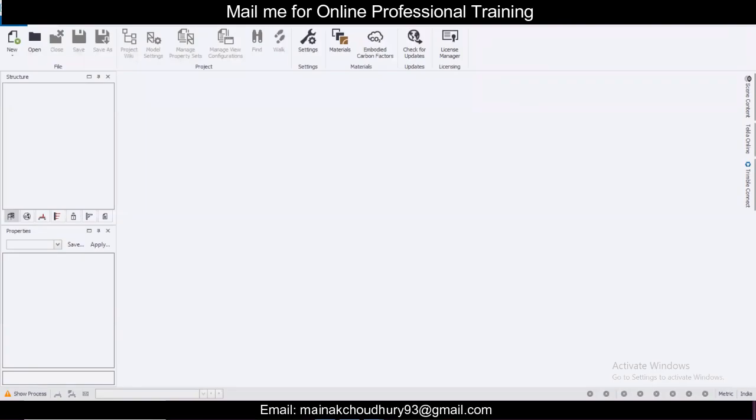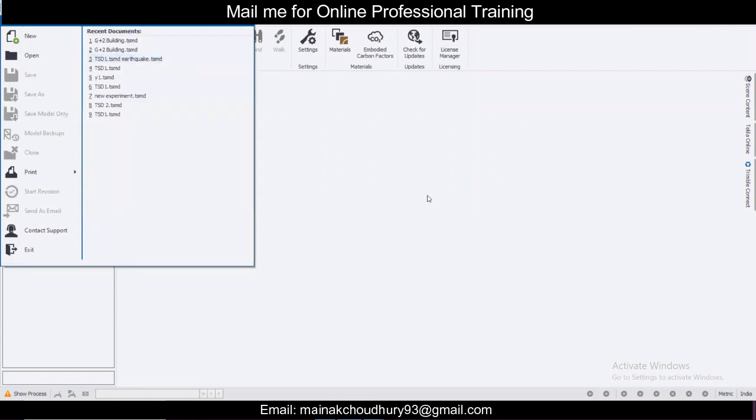So today we are going to do a new video on Tekla Structural Designer where we are going to design a portal frame, and we'll see how to do the entire process of the modeling and also apply loads in the portal frame. Okay, so first of all we need to open a new file here.